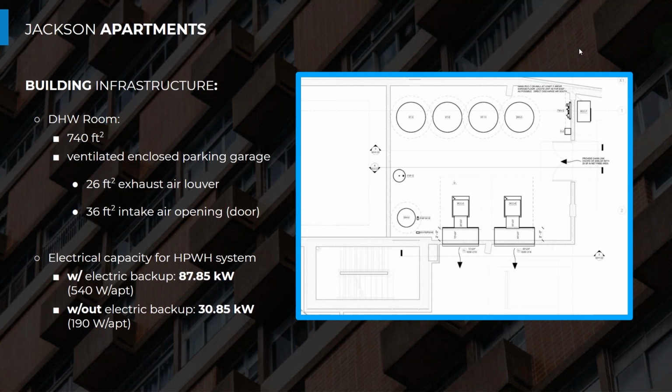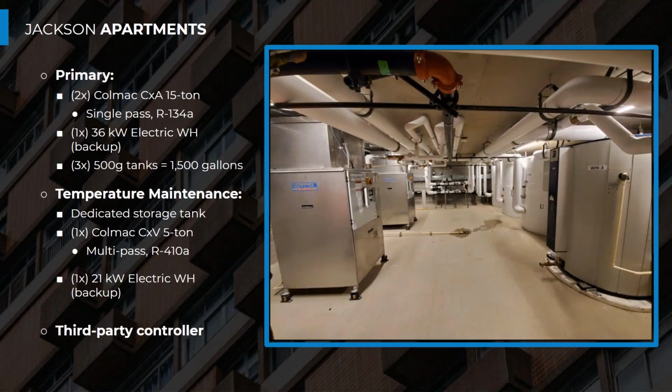Absolutely. We have seen, especially at this building, that the electric resistance kicked on, which does significantly decrease the system efficiency. However, it's very infrequent, and typically one of the issues has been a control glitch in the heat pump water heater itself that was corrected by the manufacturer with a control service update. But primarily those are kept off.